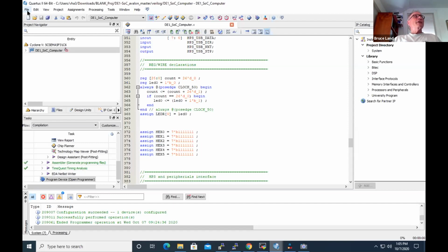The tricky thing here is, what happens if you put a divide by 10, say, in the feedback from the output to the phase comparator? Now the output has to clock 10 times faster so that the feedback loop keeps the fed back divide by 10 signal in phase with the input.